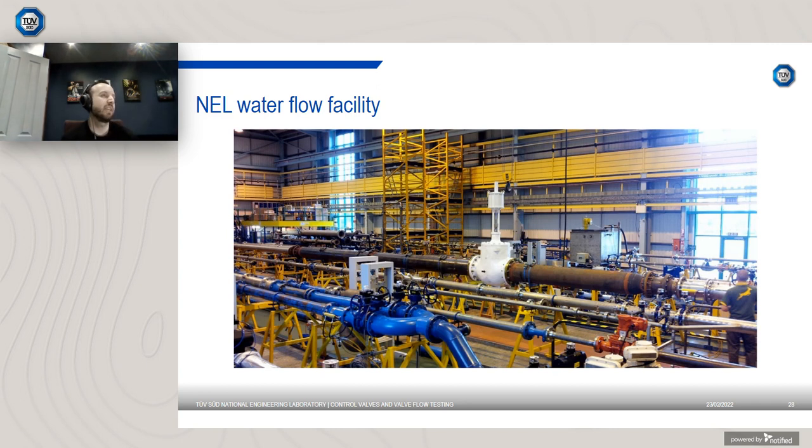So NEL tests in general accordance with both those standards. If you decide to flow test your valve, you need a flow facility. This is an image of NEL's flow facility. We've got a globe valve that was undergoing a CV test. The good thing about NEL's water facility is we're the custodians of the flow measurement standard for the United Kingdom. So all the instrumentation and flow measurement equipment is fully traceable and has a low uncertainty.